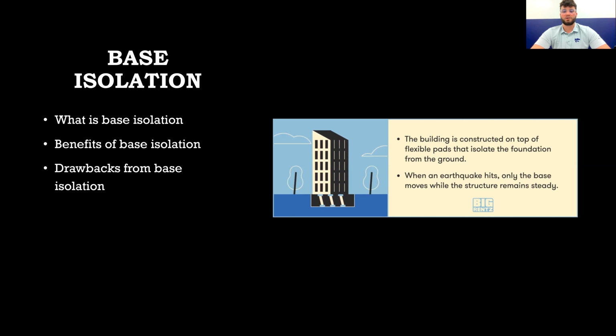The most popular application is the lead bearing. This bearing is made of a lead core wrapped in alternating layers of steel and rubber. The lead is a malleable surface and will allow the flexibility needed for the building to flex when an earthquake is occurring.